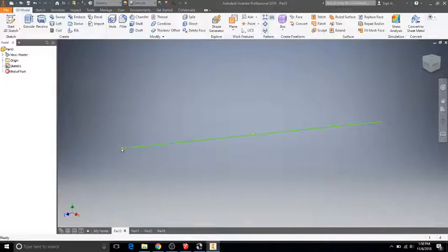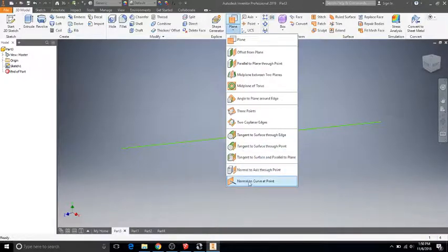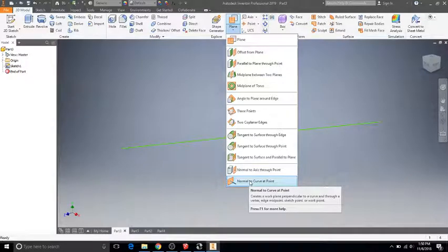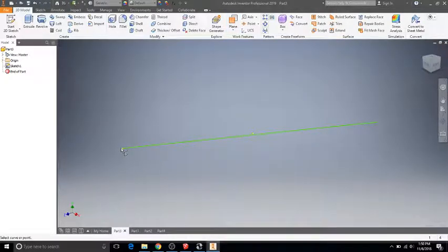To create the profile, it's almost like you're taking one of those magic bubble wands and waving it in the air to create something. To make your profile that you pass along this curve, you're going to go up to plane, normal to curve at point. What normal means is it's just like how two lines can be perpendicular and cross at a 90-degree angle. This is like a line intersecting a flat sheet of paper, and it's intersecting at 90 degrees from every direction. So like you're spinning a plate on your finger or something along those lines.